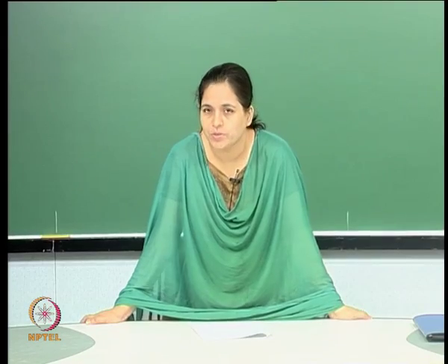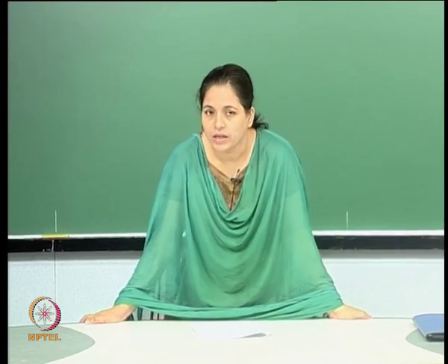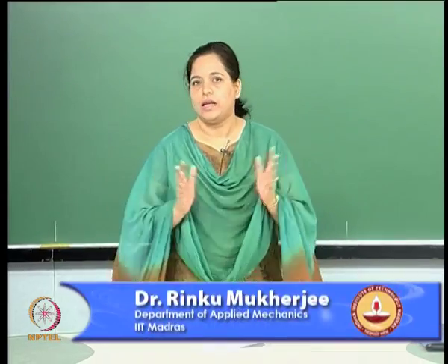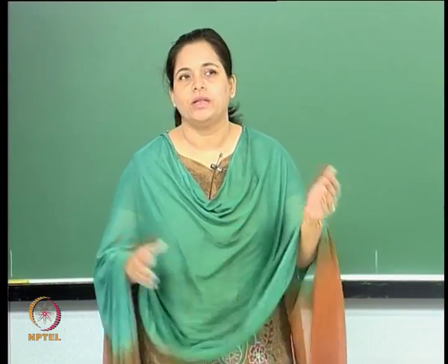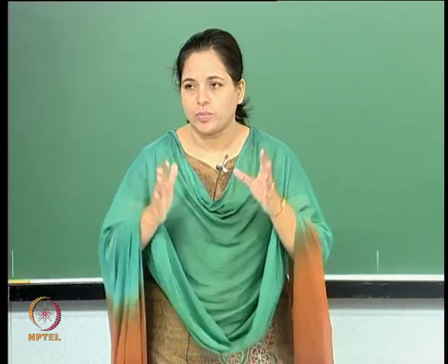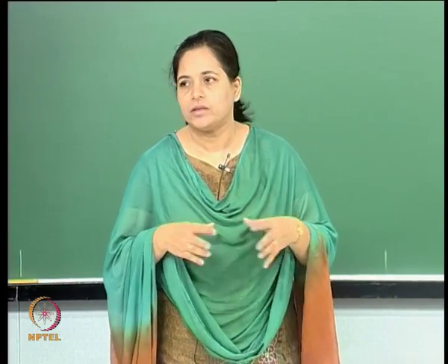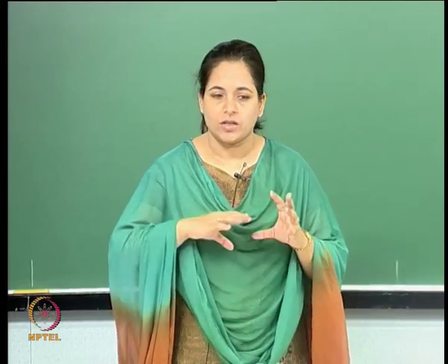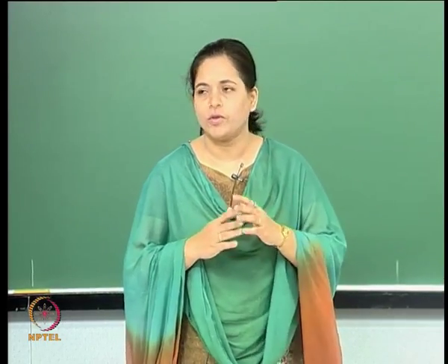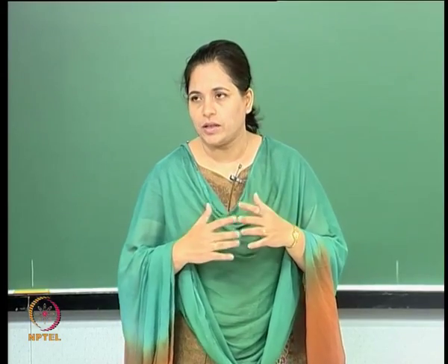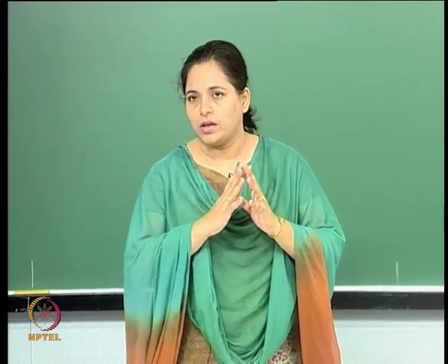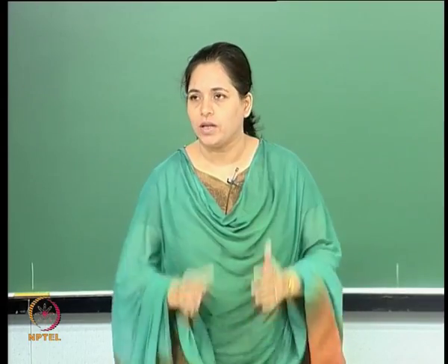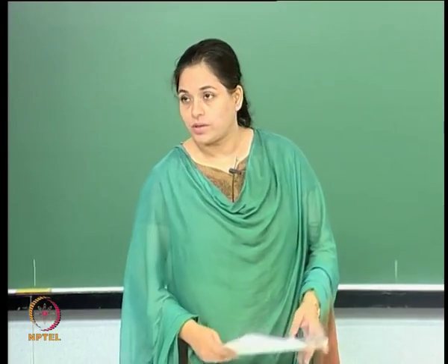That is, when the flow comes into the throat area, which is the sonic area, then it expands. And this expansion is not over a length. It could be over a length, as it is in wind tunnels, but then we decrease that length to a point so that we have a centered expansion wave. That's really the minimum length you need so that the flow diverges, and then finally we get uniform parallel flow to the walls of the nozzle. So that's where we were.